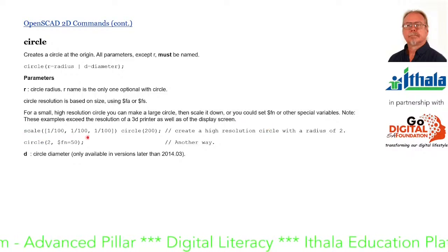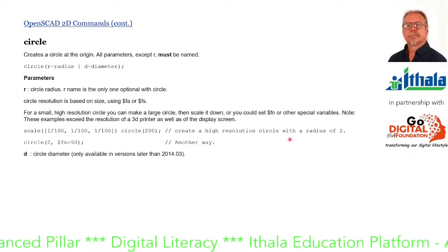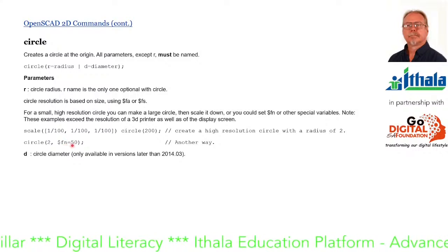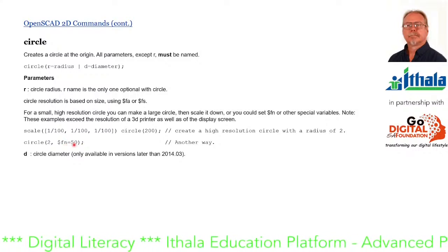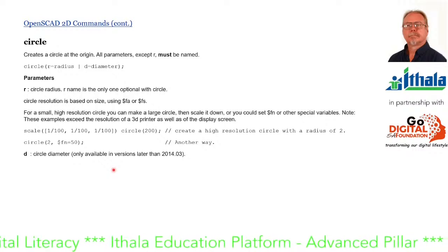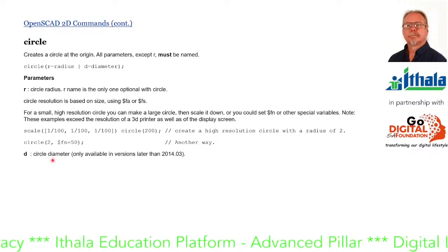Okay, so we can scale a circle to create a higher resolution version of it, or we simply specify $fn equals and then a fairly high number. Okay, d, circle diameter. Okay, so you can specify the diameter instead of the radius.